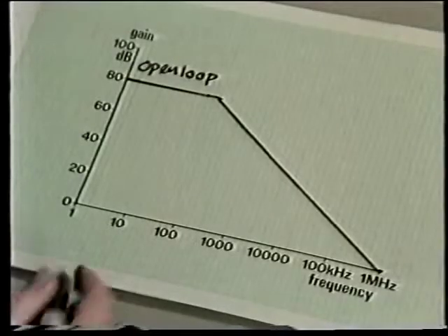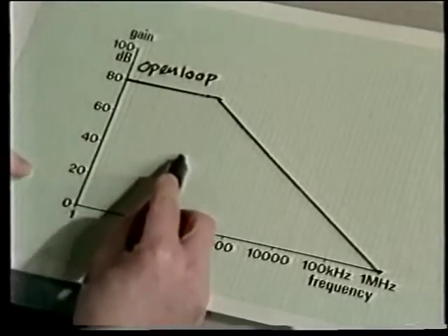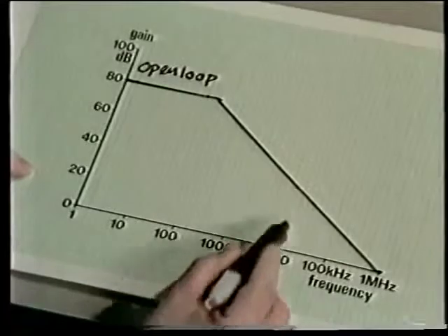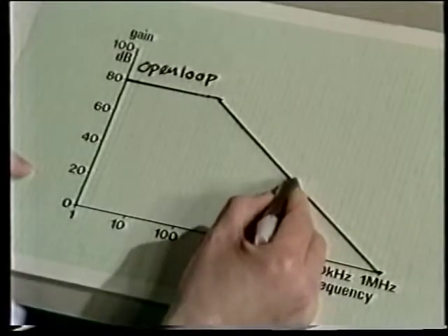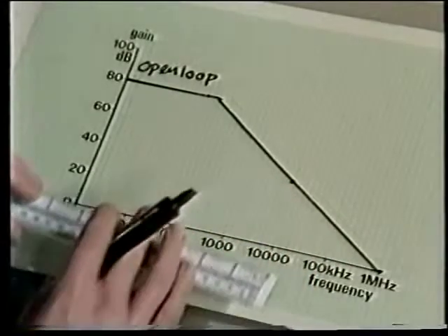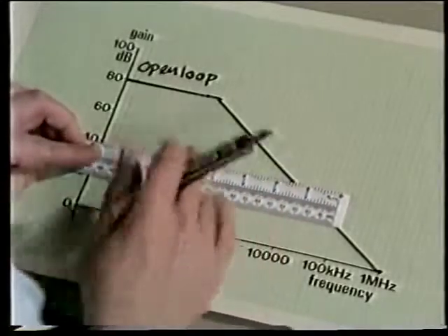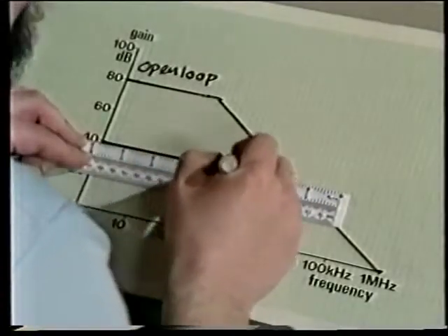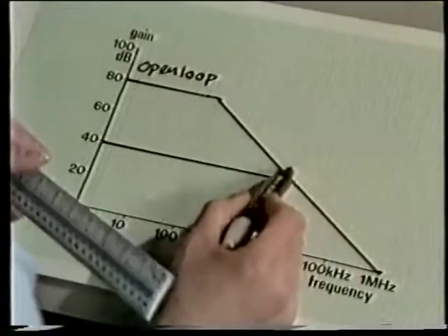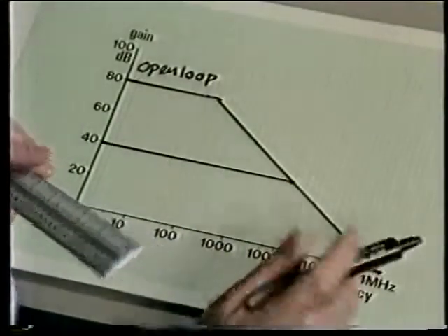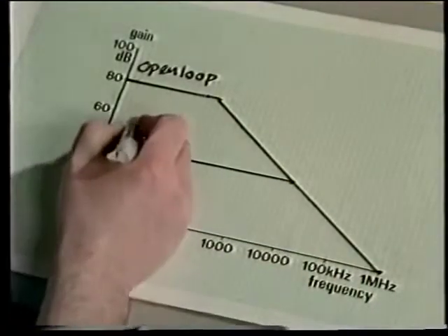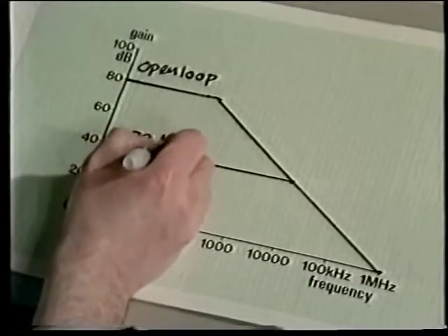Okay, Nick? Yes, the gain was 40 dB over the flat portion, and the 3 dB frequency was 10 kilohertz. It's about here. And again, I'll use just the 2 straight lines to approximate the response. And I know it went to 0 dB at 1 megahertz. I'll label this 99 kilo ohms.